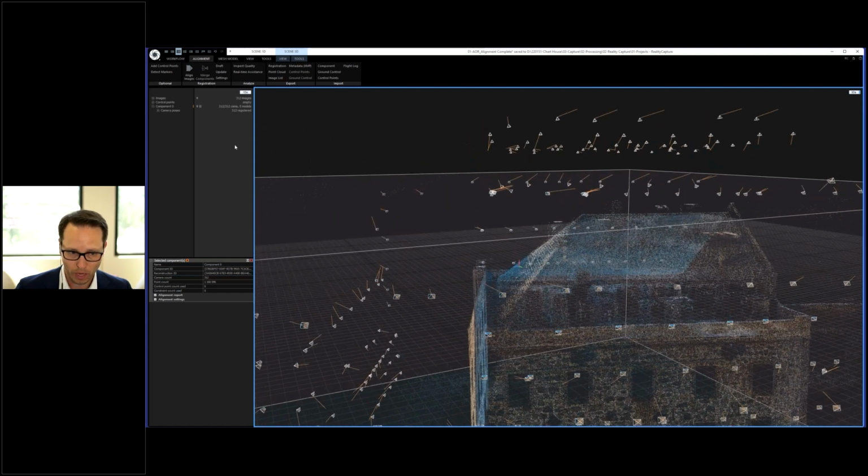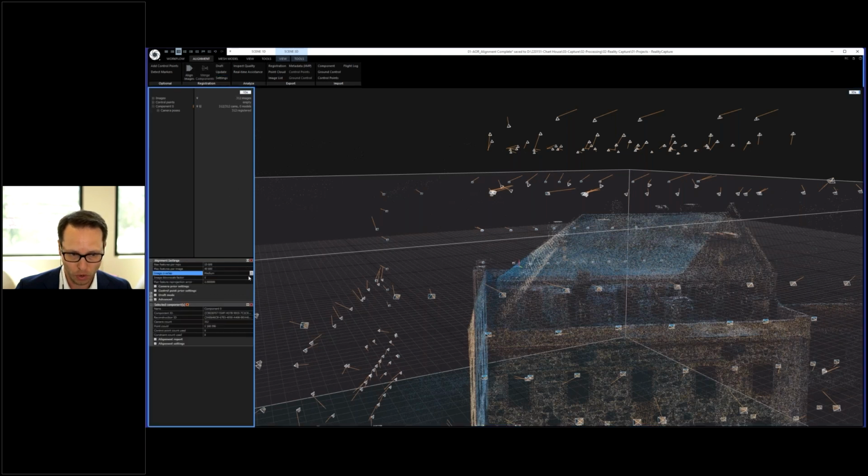You can obviously realign the photos by changing some alignment settings. You have a few options here. You can set the image overlap to low, and also change the detector sensitivity to high or ultra, and that might fix it.